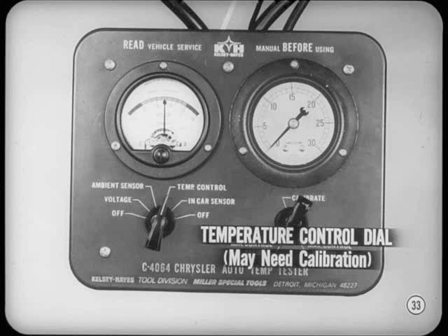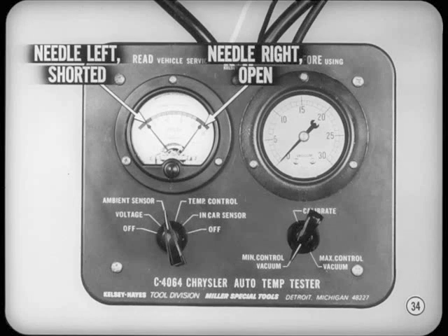It's a simple matter to check the calibration. You'll find a good description of the procedure in your service manual. Incidentally, if the needle is in the red area to the left, the unit is shorted. A needle in the red area to the right indicates an open.